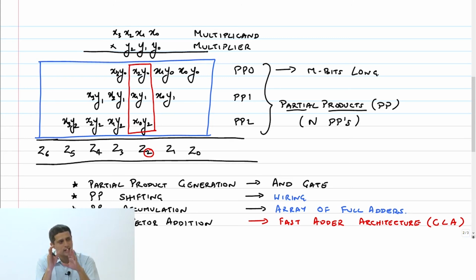Actually, in reality, if you look at a microprocessor, nobody cares if you are doing 4-bit into 3-bit. Everything will be converted into 4-bit into 4-bit. You append zeros and proceed. That's all. So this N and M is only to tell you which one is giving rise to more partial products.